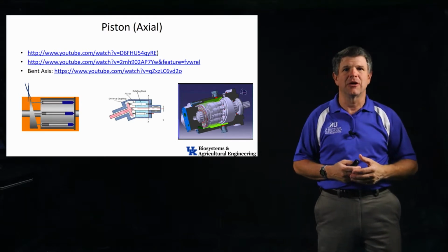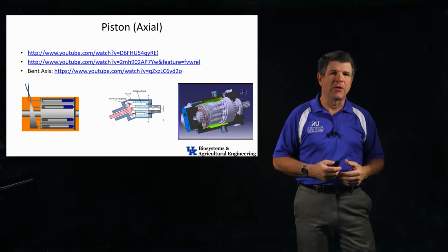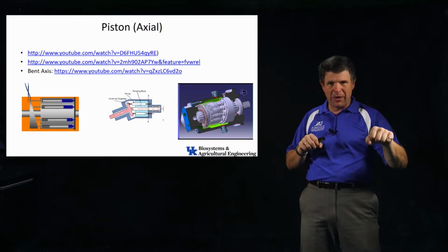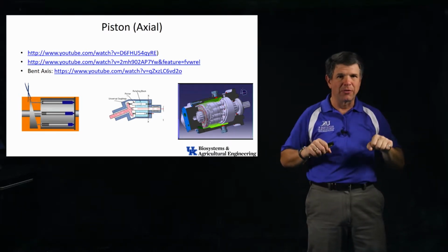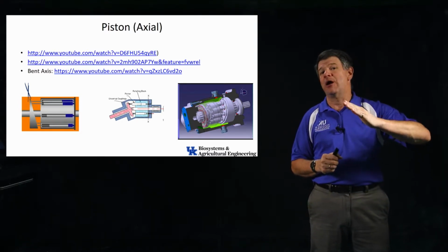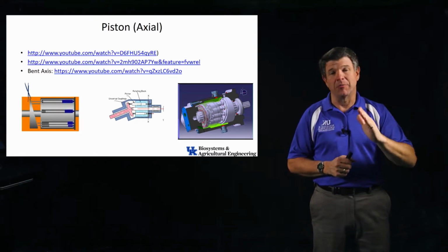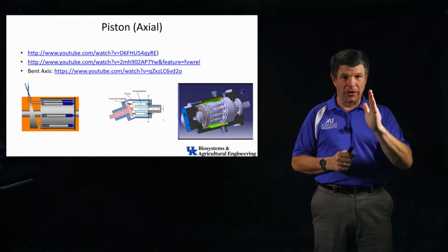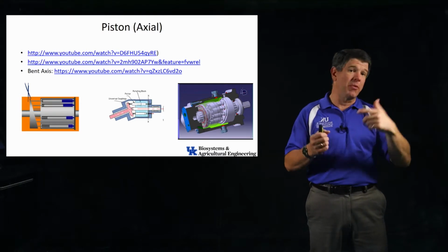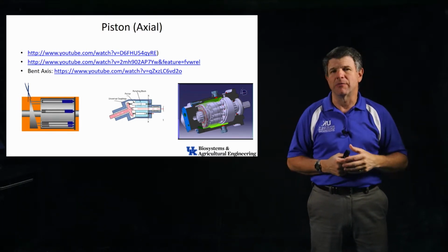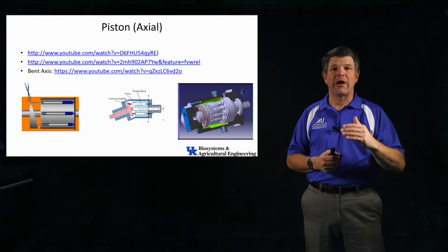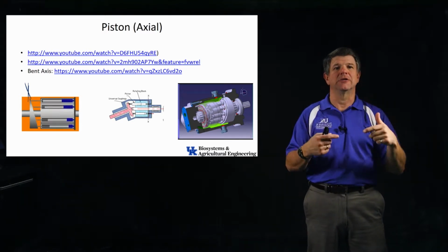My engine stays at a constant speed, but the speed of the mower goes. In the same way, the ZTR mowers that have the handles on them, and we make one wheel go forward and backwards, or both of them go forward, that's what we're doing. That handle is connected to the swash plate on an axial piston pump most of the time. And so when we want to go faster, we tilt the swash plate, we get more displacement out of the pump and the motor, or both. We actually do both of them together for efficiency reasons, and that's going to increase the speed, make me go faster. I bring the swash plates up vertical, I slow down and stop.